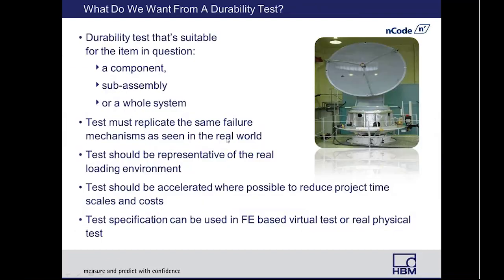So now we're talking about qualification tests, durability tests, vibration tests. What do we want from such a test? Basically, such a test must replicate the same failure mechanisms as the ones seen in the real world. Also, the test should be representative of the real loading environment, and the test should, if possible, be accelerated to reduce project timescales and costs.